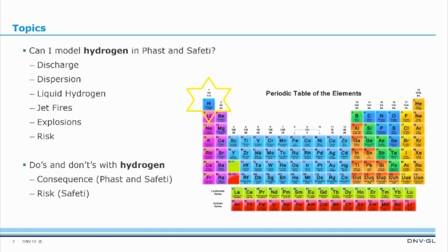However, it is a rather extreme material, and it's a fair question to say, how good is Safeti and Phast for modeling hydrogen, and especially in the light of research in recent years. When Phast and Safeti were first developed, to my knowledge, there was very little in the way of data and models that focused on hydrogen. It was more focusing on hydrocarbons. So the models in Phast and Safeti are largely derived from hydrocarbon data.